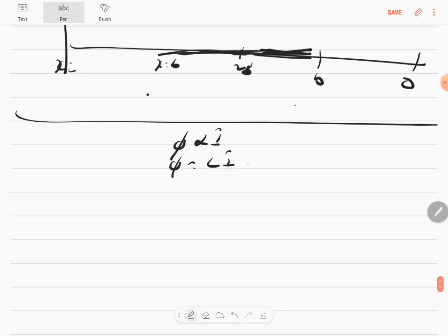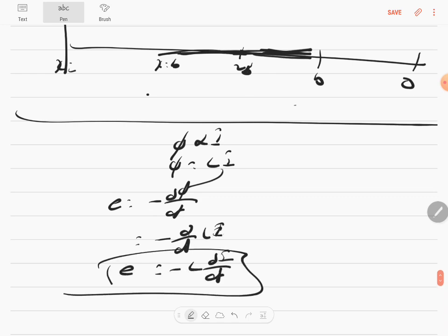So if you take this and put it in Faraday's law, E is equal to minus dΦ/dt. Instead of flux, if I put Li, it becomes minus d/dt of Li. So minus L into di by dt is the EMF. In the first part of the lesson you get minus N into dΦ/dt; in the second part of the lesson you get minus L into di by dt.